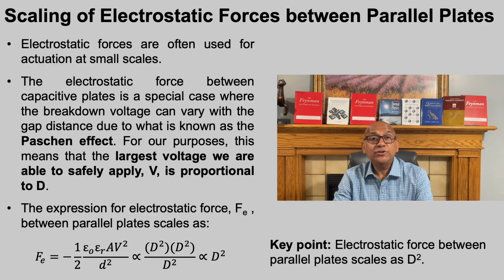Electrostatic forces are extremely important at small scales, especially for actuation in nanoscale and microscale devices. Now let us look at the case of parallel plates. The electrostatic force between capacitor plates is slightly special because the maximum voltage we can safely apply depends on the gap between the plates.